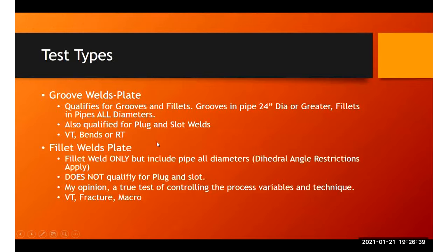For the fillet weld plate test, the fillet weld is all they're qualified for, but it does include pipe for all diameters. I guess in the dark you probably can't see my hand gestures, but anyway, someone that does the fillet weld break test is qualified to weld on pipe of all diameters for fillet welds. There are restrictions for the dihedral angle for how the pipes come together, but as far as for a fillet weld, they can do any size. Doesn't matter. But it doesn't qualify them for plug or slot welds.